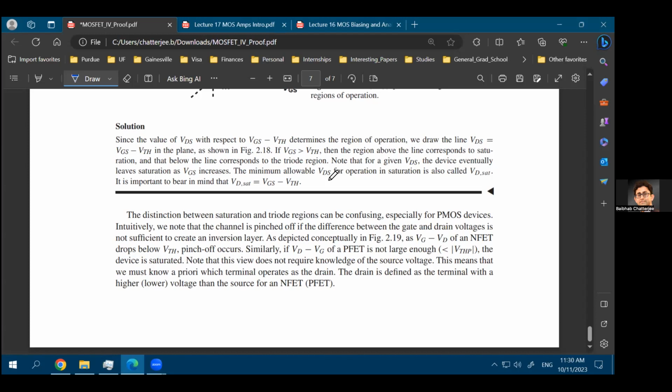Unless you apply the current in the drain terminal. In that case, the current that you apply in the drain terminal will flow to the source terminal, or the current that you apply in the source terminal will flow to the drain terminal. So you have a current amplification of 1, and you cannot get a higher current amplification factor. You cannot create additional current. That's why MOSFETs are not usually used for current amplification. BJTs are used for current amplification.